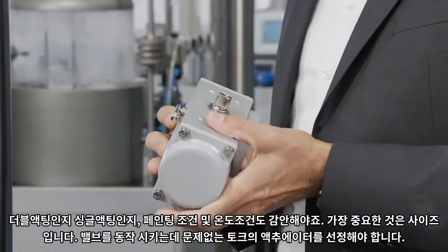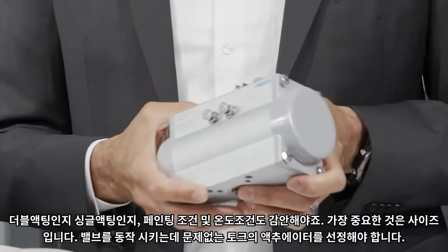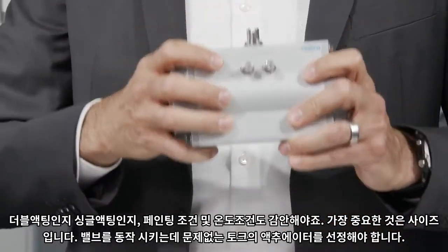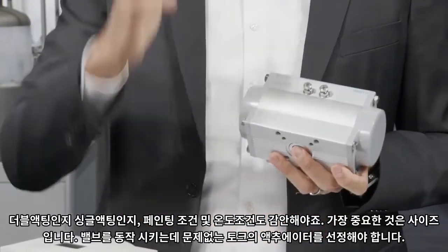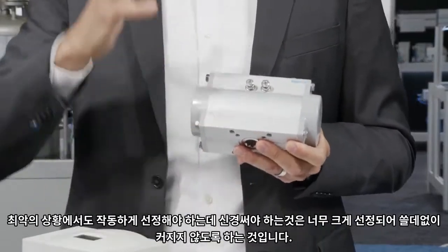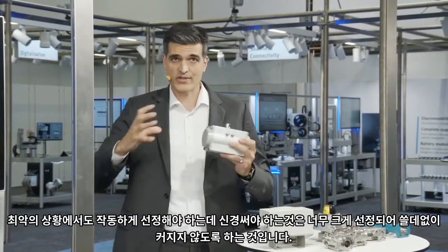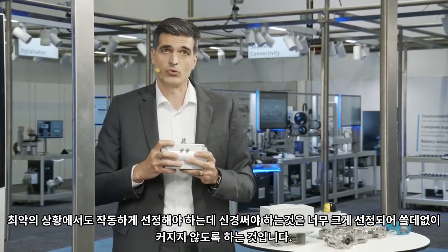Besides the fact that you need to choose if the quarter turn actuator is single acting, double acting, maybe you have to select coating and range temperature. The critical and the most important part here that you have to do is sizing. You need to do the right sizing of the actuator in order to be sure that you will be able to operate, to move your process valve under the maybe critical conditions that you have defined. But attention, you need to do the right sizing, but you have to avoid oversizing, since this will lead to unnecessary overcosting that you want to avoid.